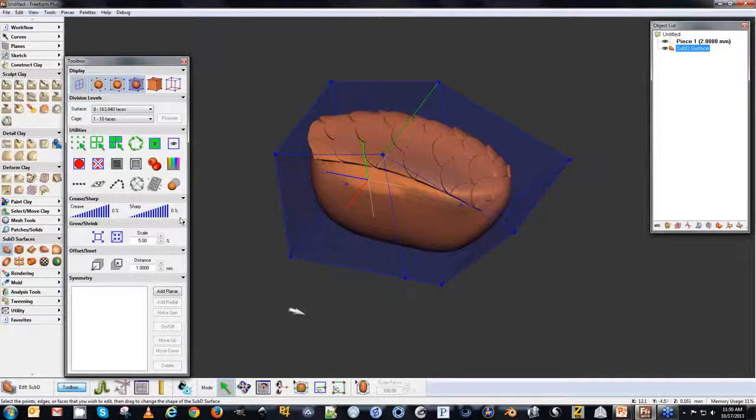Let's say we need to design a part with a specific tolerance to mate to, for instance, a metal ball joint. Currently, the part was designed with SolidWorks. How could we make that part in sub D with a specific tolerance we can adjust when needed? That is one of the shortcomings of sub-D modeling. It is a lot more difficult to meet specific tolerances. You can convert to clay, you can get a rough base object in there and then move to other types of geometry in order to meet what you're going to do, but it's not easy to do directly in sub-D.